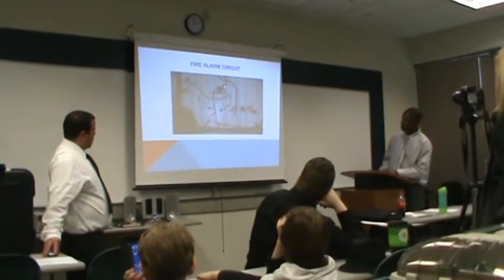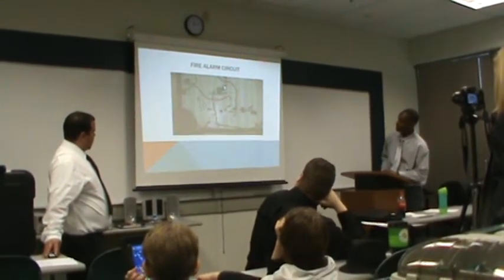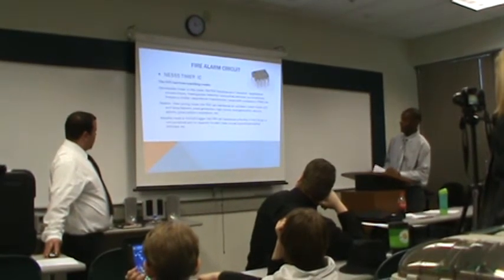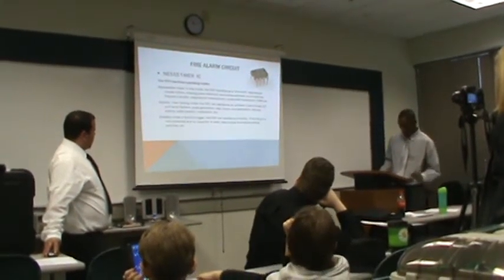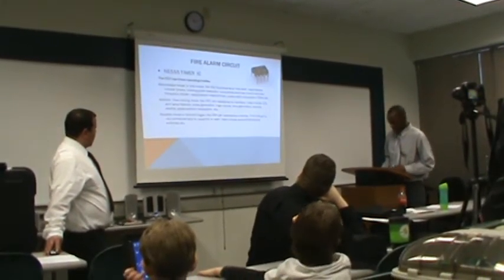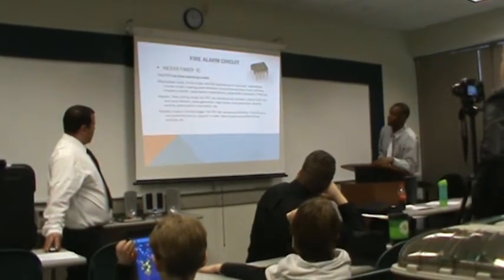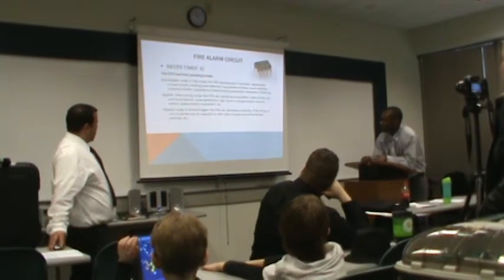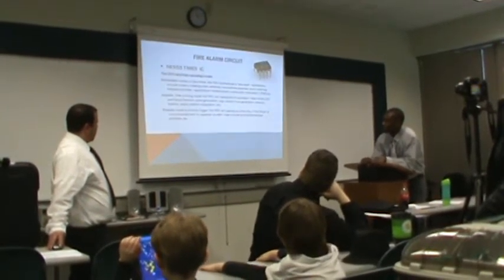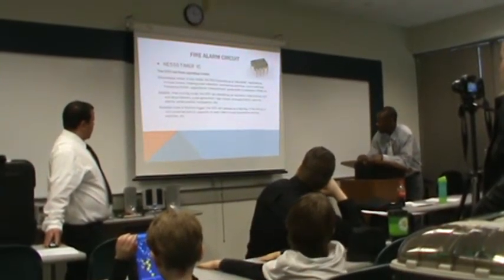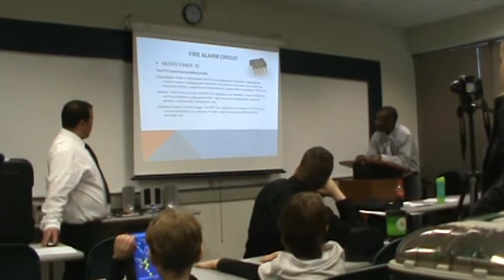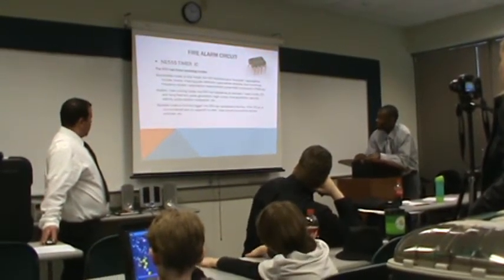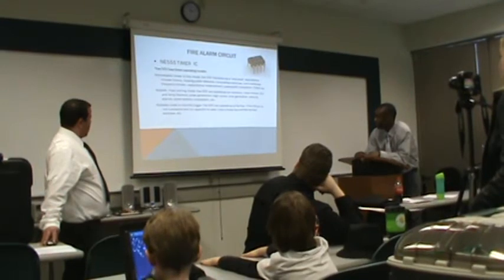That's the actual fire alarm circuit, and the NE555 timer IC chip. It has 3 operating modes. Monostable mode is where the 555 functions as a one-shot. Applications include timers, missing pulse detection, bounce-free switches, touch switches, frequency dividers, capacitance measurements, and pulse width modulation.